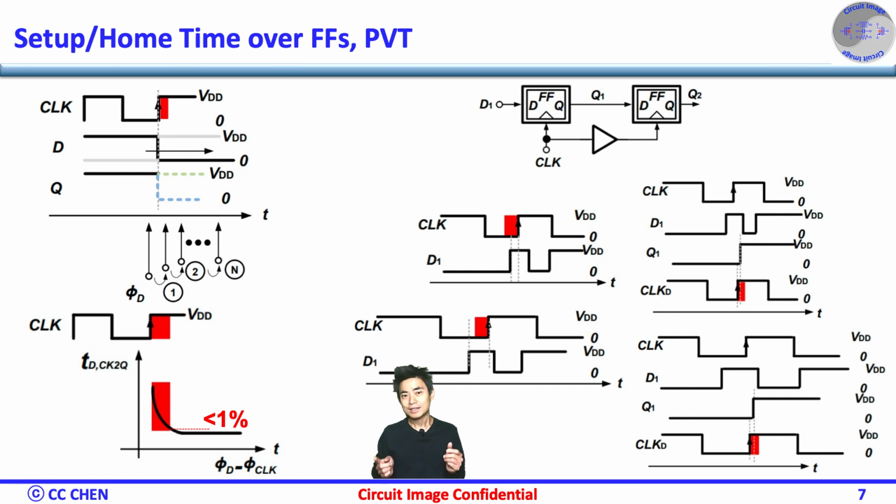As you can see, the bigger bit period will lead to a longer arrival time than the setup time. Therefore, the setup time is easier to meet at a lower speed, but the arrival time after the clock edge is the same, no matter what the bit period is. Then, if the data transition after the clock edge violates the hold time, it doesn't matter if the bit period is greater or less.